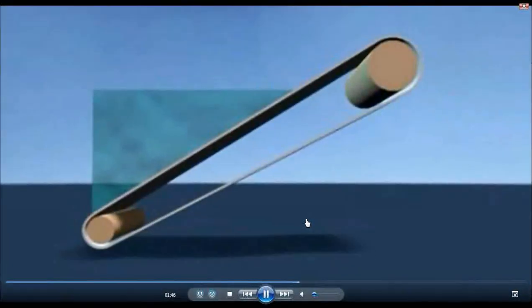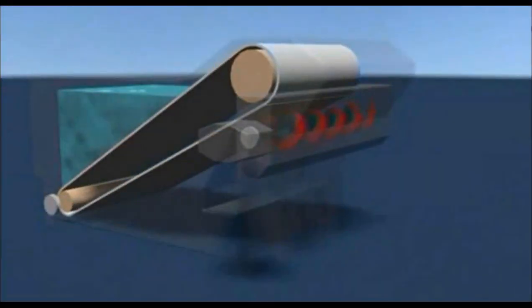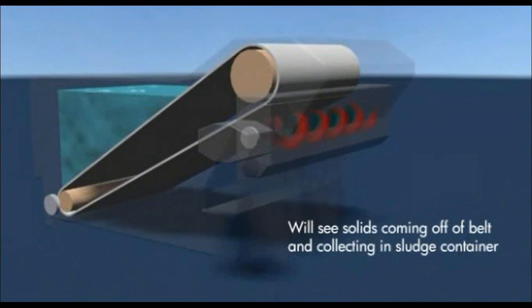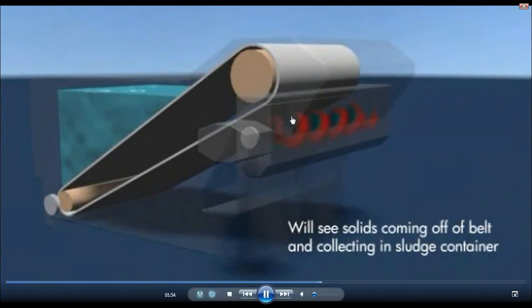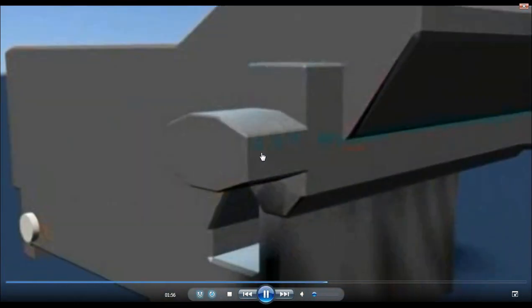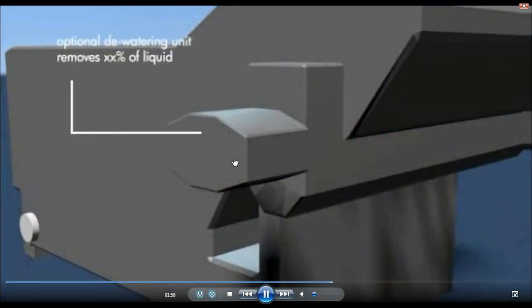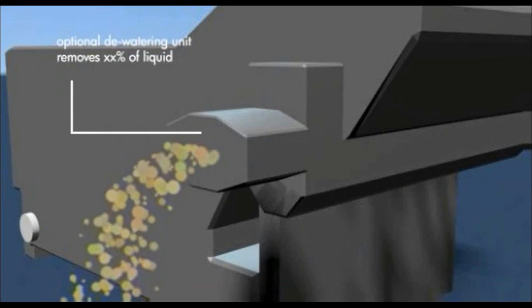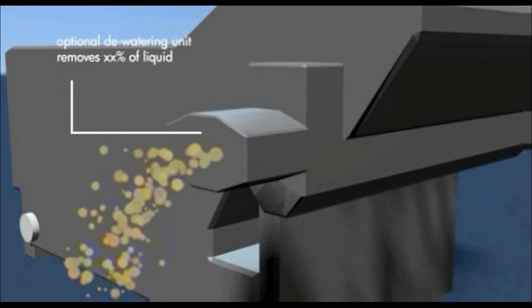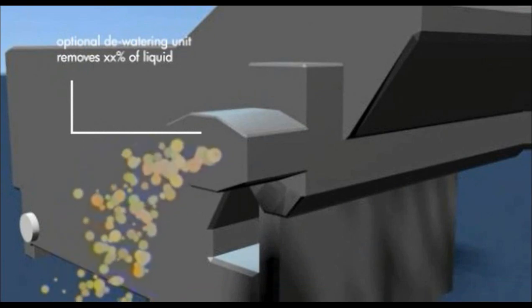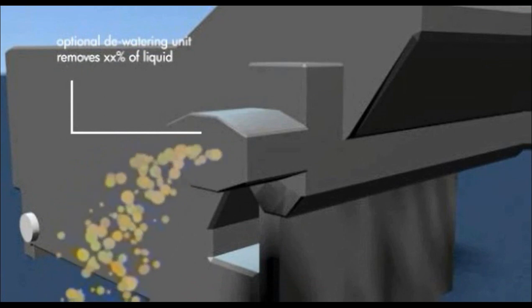effluent water. So this package, this cartridge, can again be mounted in a steel containment like this, which is fully contained for odor control, etc., and conveyance of sludge. So the sludge is moved by a screw, and there's integrated and optional dewatering that can be integrated on all of these systems that can take it to roughly 30 to 35% dry solids.